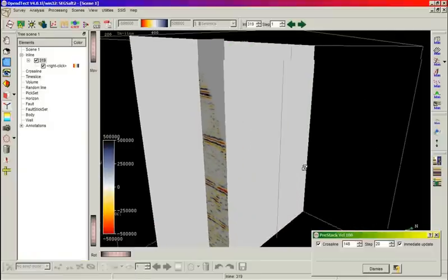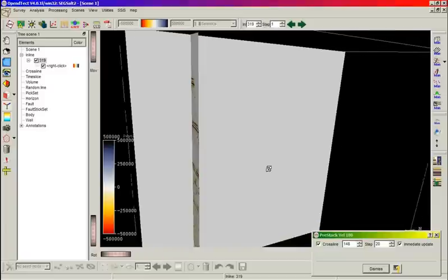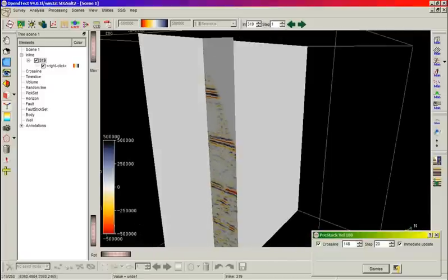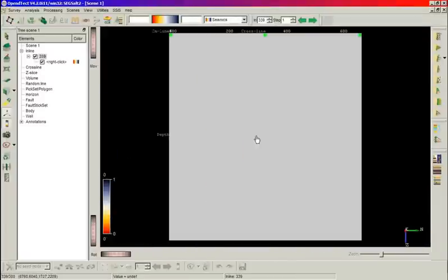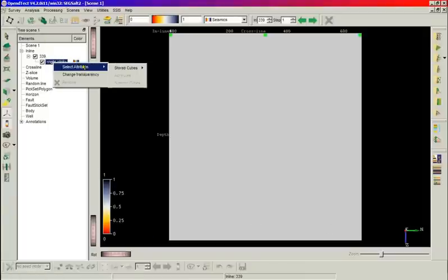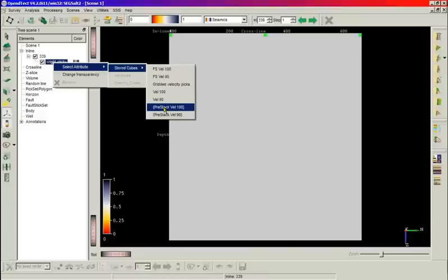Now we are more or less done with the display of the pre-stack data. There's one more option that will be available in version 4.2 of OpendTect. On an empty plane like this, it is possible, when looking at the list of stored cubes, to display the pre-stack data. You'll see your pre-stack data marked with curly brackets. Without curly brackets, these are normal post-stack data volumes containing either seismic data or attributes or velocities. But we can also see the pre-stack data.